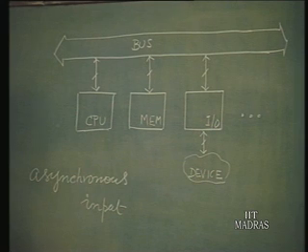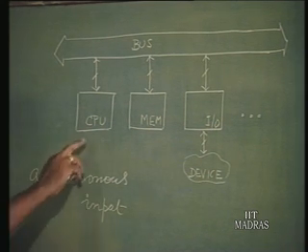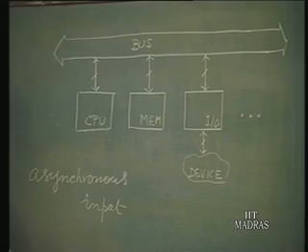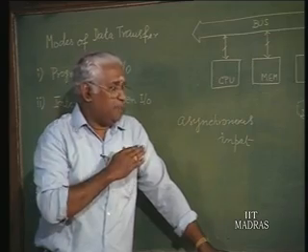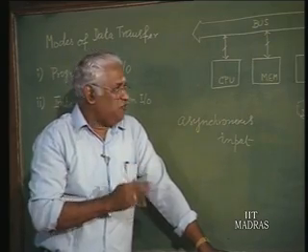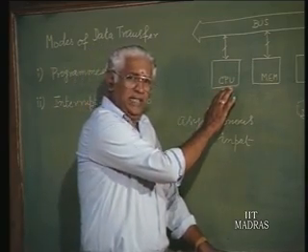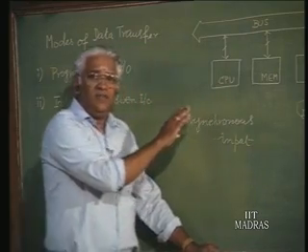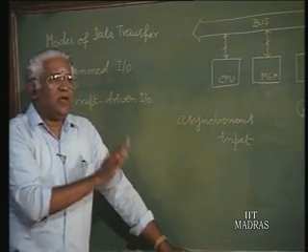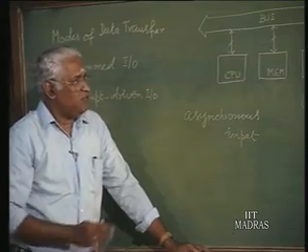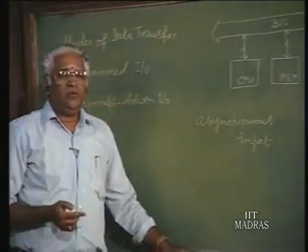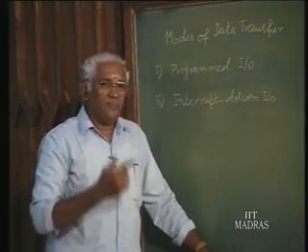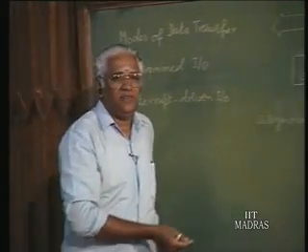And when can the CPU be interrupted? We saw this also in the previous lecture. We saw that the CPU should complete the current instruction cycle and then only take up the interrupt, that is, prepare for the context switch, which means there is some more delay. In the current instruction cycle itself there is some delay, is it not, because it has to be completed. So, we saw that. There is some delay in the CPU turning its attention away from the main thing to the specific device.